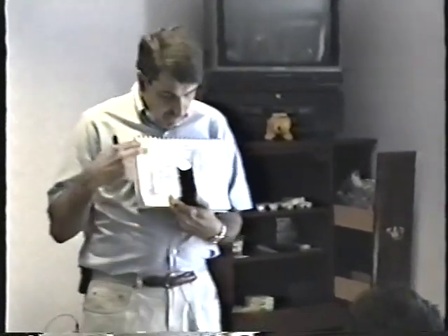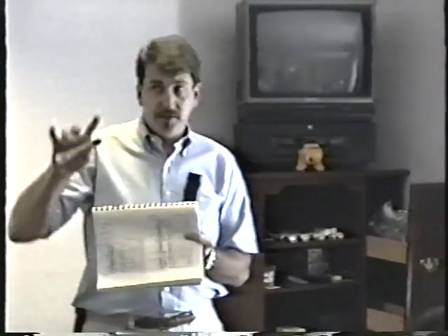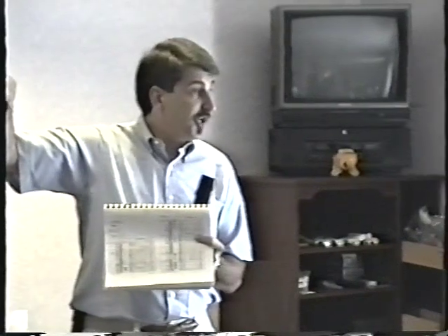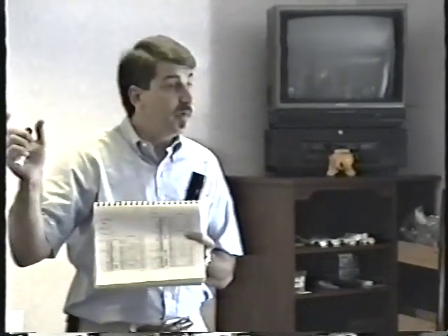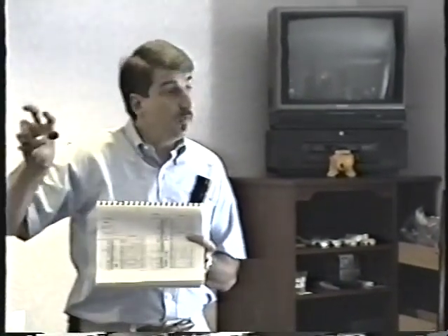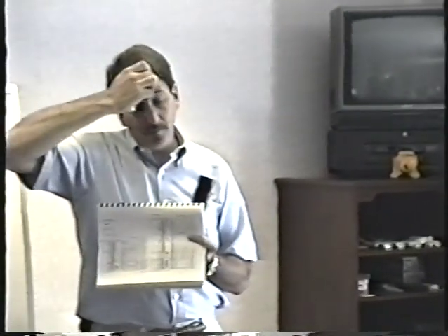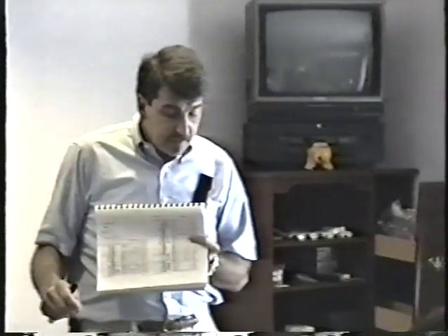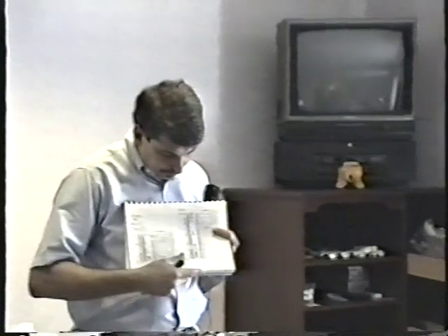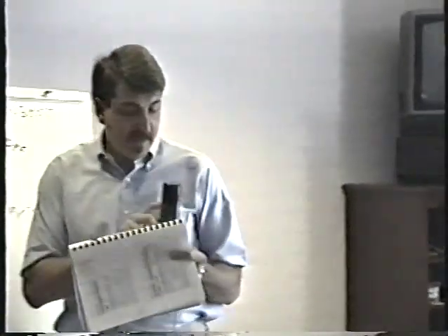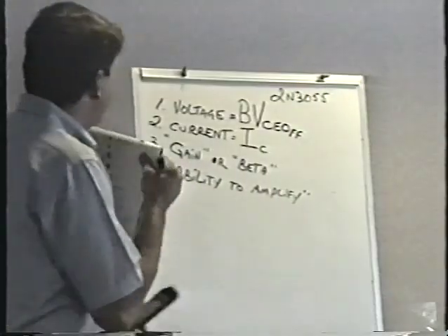But we use complementary pairs occasionally. For instance, in a jukebox amplifier, there are usually two output transistors for each channel, left and right. Those are almost always complementary pairs. One's NPN, one's PNP. It's what they commonly call a push-pull circuit. You don't really have to know that either. But two transistors, same specs, opposite polarity. They're not interchangeable.